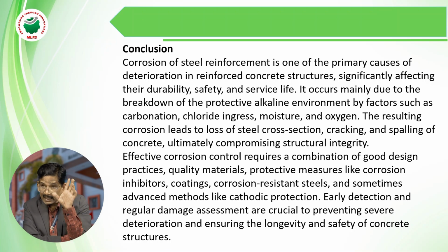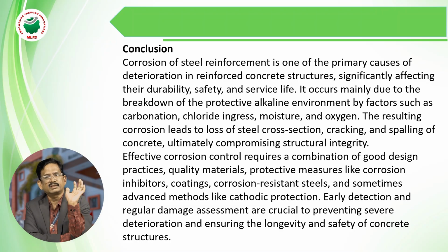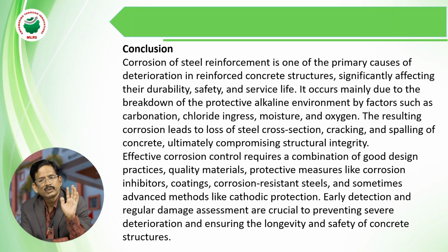And finally, early detection and regular damage assessments are crucial. I already told you this is one of the very, very important points. Early detection: suppose sometimes we are doing the concrete of the columns and the cover is missed. Immediately on the next day, whenever removing the shuttering, we have to apply some epoxy or some plastering so the rods are not exposed to the atmosphere. When the rods are not exposed to the atmosphere, automatically corrosion will be arrested. So that's why early detection is very, very important.